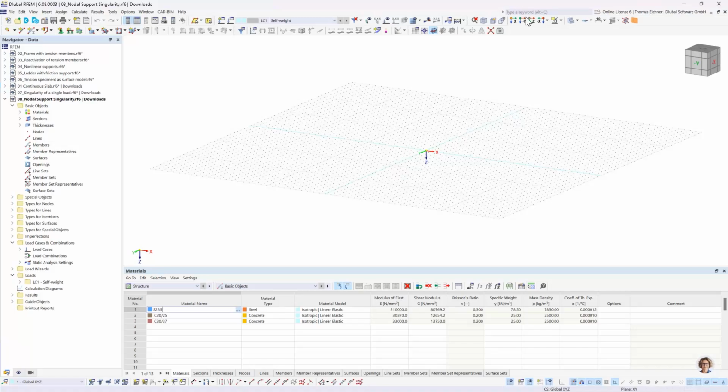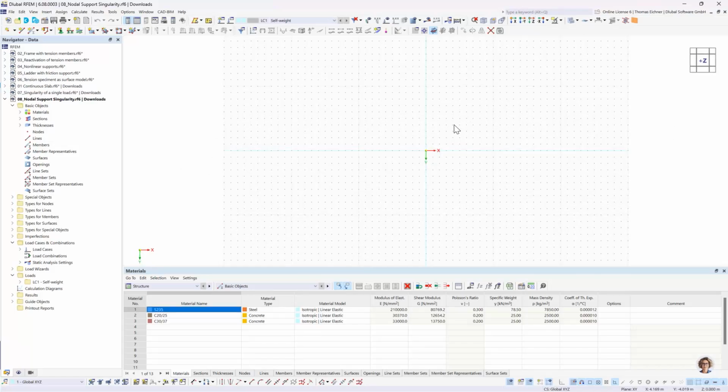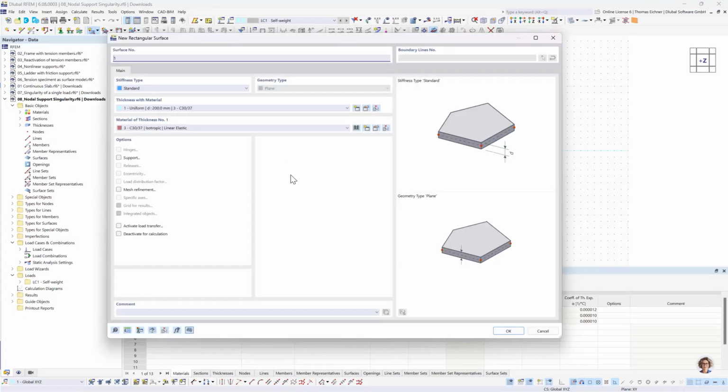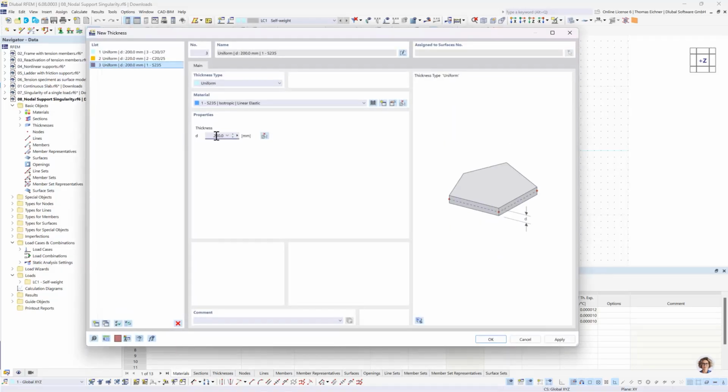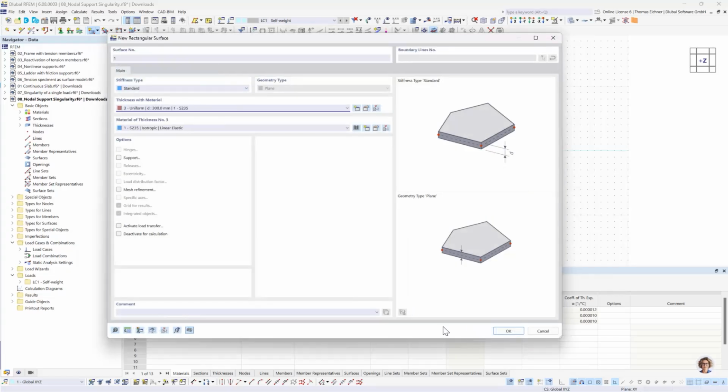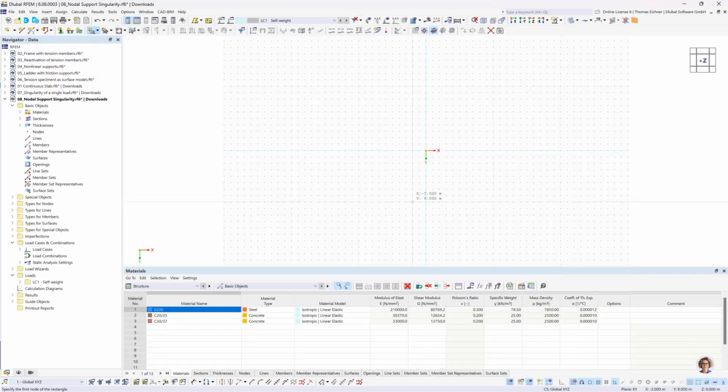And there it is. Again, we're gonna go for 4 slabs here. Let's just start right away. This time it's quite easy. The only thing I wanna change is here. I wanna go for 300 millimeters again. Okay. And stay with this C30/37. Press OK. And then we can